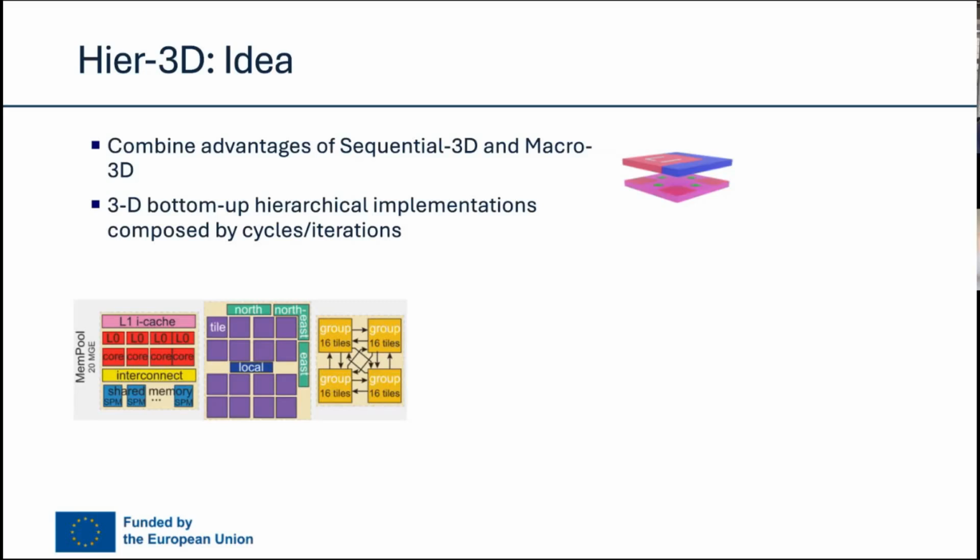Note that since the system is asymmetric, so the area of the bottom tier is larger, we are reserving some area in the top tier that we will reclaim in the following iterations. Also, you see that there are a couple of small green points. These are some areas that we are reserving already so that later on the implementation of the system is easier in following iterations. Once we have this partition with this space reserved, we can adjust the normal flow that we have seen before to complete the tile.